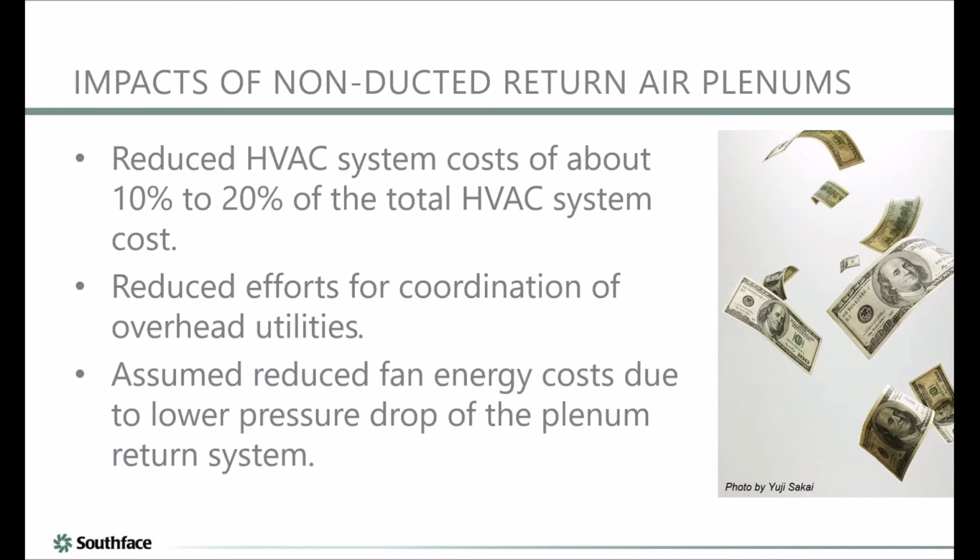And this last bullet, there are some Benjamins floating around to represent the savings, and we'll come back to that. The idea is that the cost of operating the fan system is going to be reduced because you're getting a lot of return area, so it's low pressure drop, and that's lower fan energy. To some extent, I think that's true.